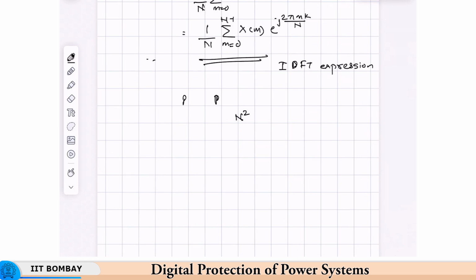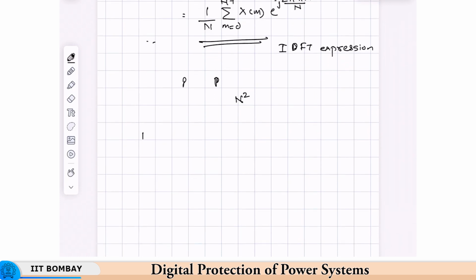Now, for an n phase system, this sequence transformation, say the symmetrical components, will have the 0 sequence component, there will be a positive sequence, and then there will be n such symmetrical components. For a 3-phase system, there will be positive, negative and 0. For any other n phase system, the positive and 0 sequence will exist, and then there will be other components which will make up the n symmetrical components. We are more used to dealing with the 3-phase system, so we talk of positive, negative and 0, but even in a 4-phase system you will have 4 components. There will be positive and 0, and then there will be 2 in between.